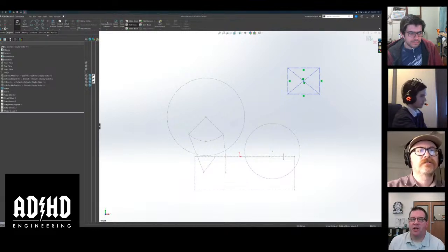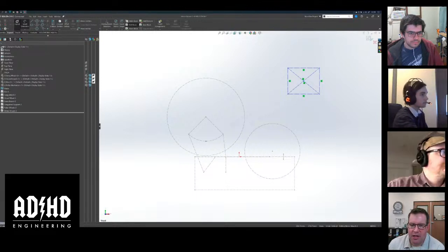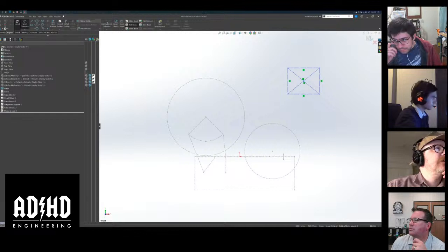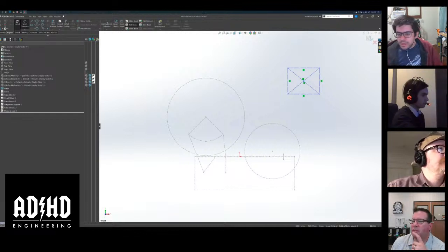And all I need to do now is give it dimensions. For clarity, you clicked on edit the block because now we have the blocks in the feature tree at the bottom, right? Yep. You didn't go back into the layout and select it. You just selected the named block, correct? Yep. Okay. Sorry. Proceed. You could also do it up here, because this layout tab has all of the stuff you're going to need for that. So now in this view, you can click on the insertion point and then just do a fixed constraint. Try it.